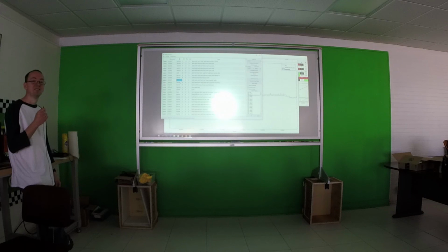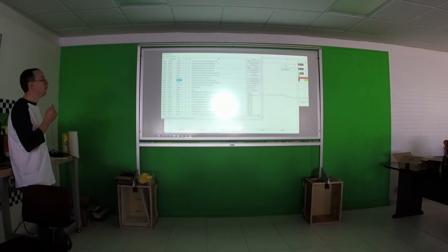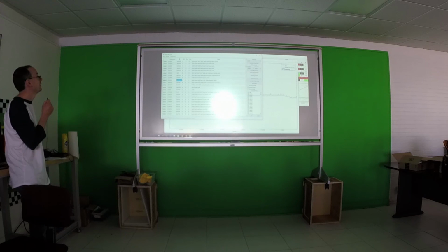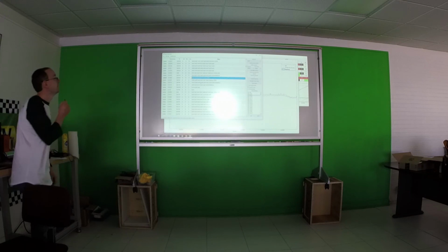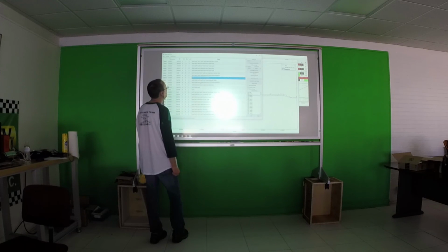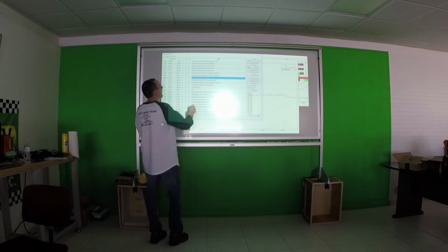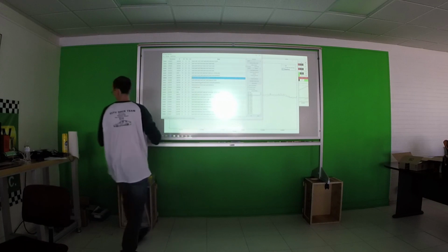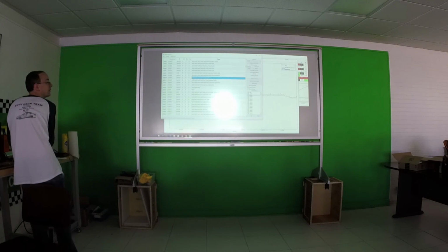It's a chicken and egg question, but would this software suite, as you've got it, have sped up the cracking of the UQM? No, not really. What I did for, I don't know if there's an easy way for me to show it in here. Gear on the Tesla does have a security byte. This final byte here is the security byte, 7F. I had to crack that too. What I did is I'll filter to only 228 so we can show how that process works real quick.